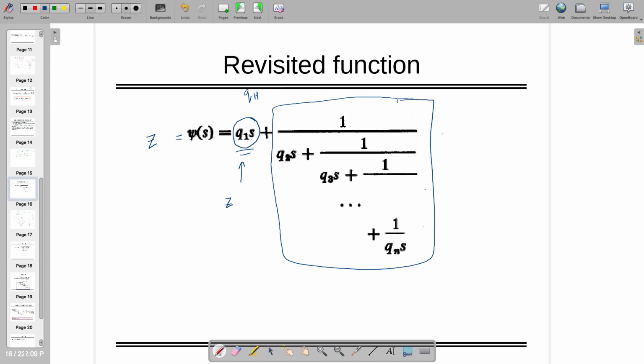Is it impedance or is it admittance? It's admittance because it's 1 by something. First part is impedance, and then you are converting that to 1 by something that is going to give you an admittance entry. Again I am adding with impedance, again admittance. So it's a combination of impedance and admittance. That is what you need to formulate in your circuit.